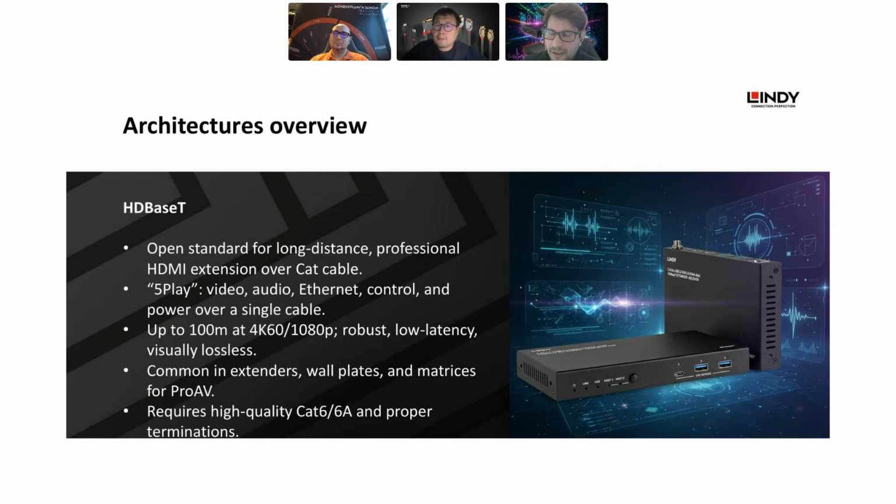A CAT6A cable, we recommend. Up to 100 meters at 4K 60 Hz or Full HD. Low latency, visually lossless. Common in standard wall plates, matrices, and Pro AV environments. Requires high quality, as I said before, Cat6, Cat6A cable. In some cases, HDBaseT Cat6A cable certified.